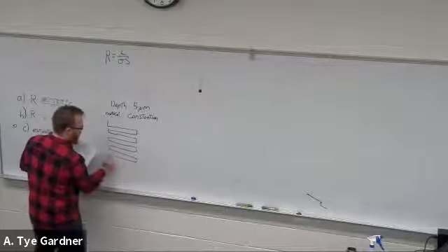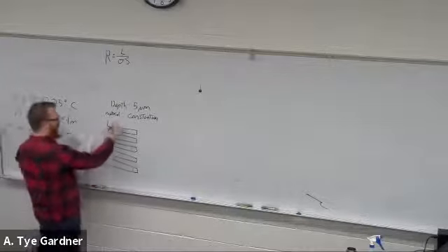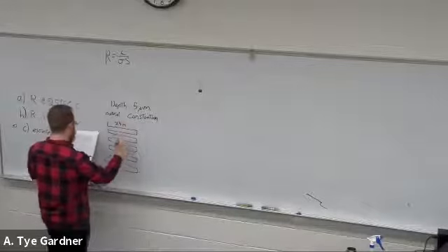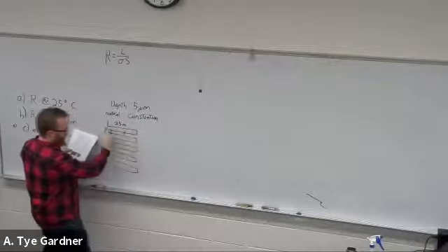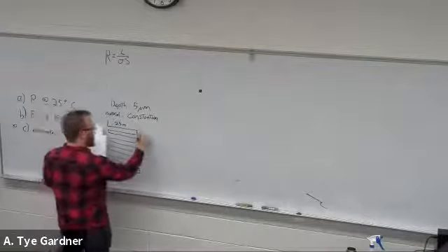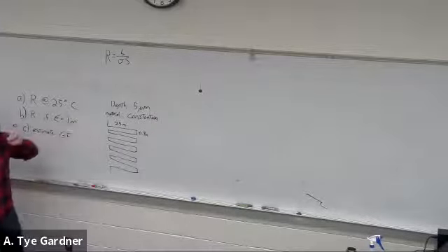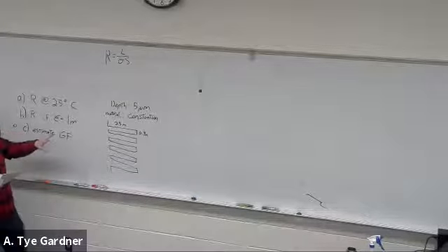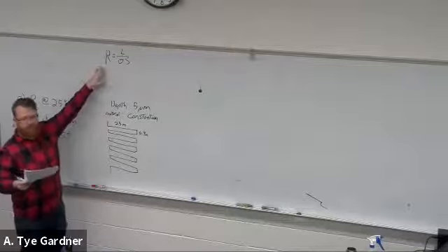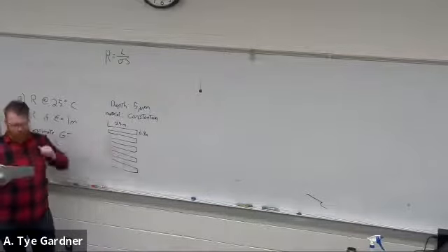Okay, this is our strain gauge, with a length of 25 millimeters, and this other length is 0.9 millimeters, right? Because we need to know the length to normalize anything. We also need to know the length in order to calculate the resistance, because sigma is conductivity, and we need to know how long it is to end up with the total resistance. The longer it is, the more resistance we end up with.